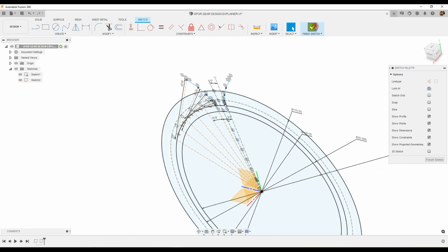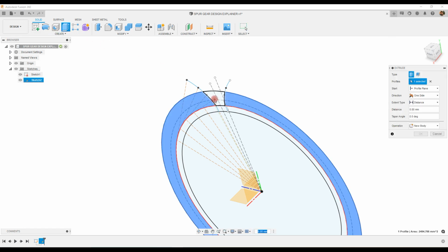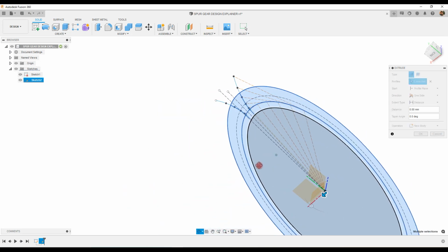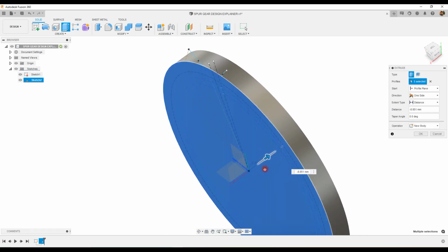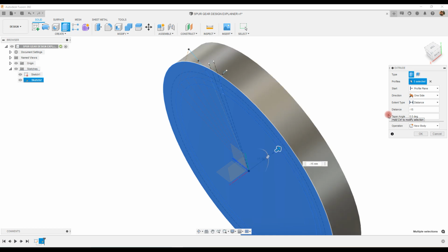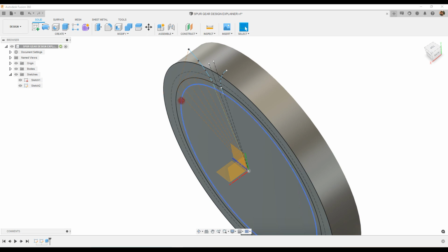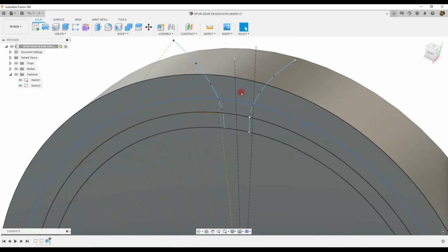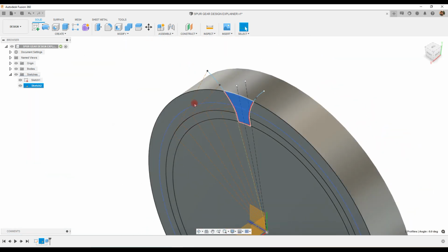Next, we create the solid cylinder for the addendum from which we can cut this profile out. For that, let's come out of the sketch, go to extrude, and select all of the profiles to form the solid cylinder for the addendum. So this will be the addendum cylinder. Extruded, let's have a width of 15 mm for the gear. Unhide the sketch again, since it will automatically get hidden. And now use this profile and this profile to cut the solid.